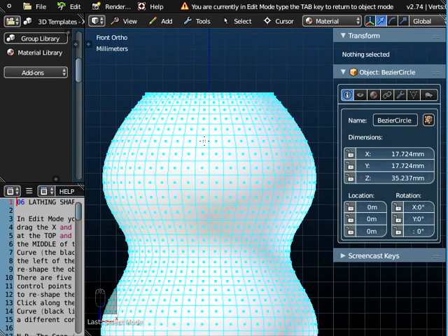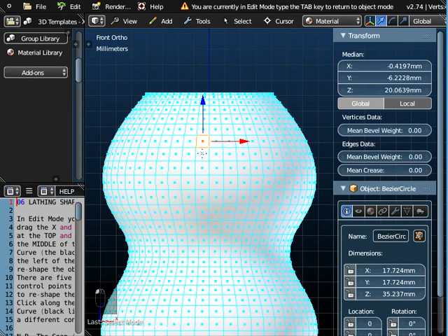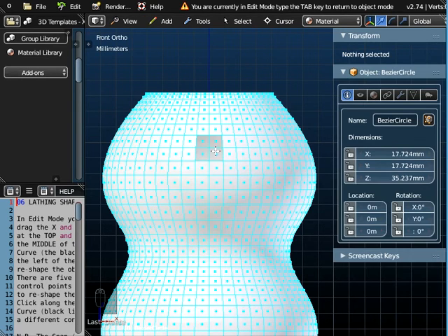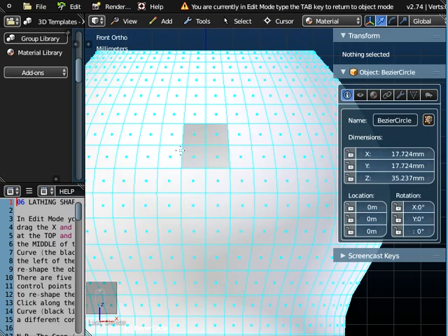And so what I want to do is highlight one, and now I need to hold down the shift key here. So highlight one face, two faces, three faces, four faces. Yeah, four faces. I did that by holding down the shift key, and I want to delete all those four faces, and we do that in FluidDesigner by pressing X on the keyboard and delete the faces. And as you can see, there is a different colour now.